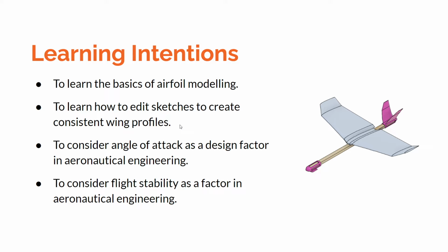So we'll be getting our NACA profile sketch. We'll be creating construction lines. We'll be tracing over that with a spline tool, then sizing it properly within the constraints. And the constraints in this video need to be adhered to because our machine has size constraints as well.